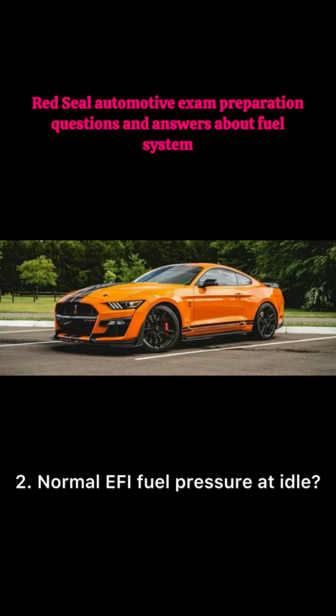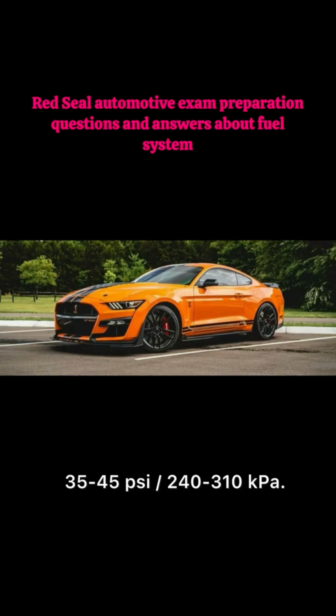2. Normal EFI fuel pressure at idle. 35-45 psi, 240-310 kPa. 3. Pull vacuum hose off regulator. What happens? Pressure goes up 5-10 psi. 4. EVAP purge valve job. Sends stored fuel vapors to engine to burn.